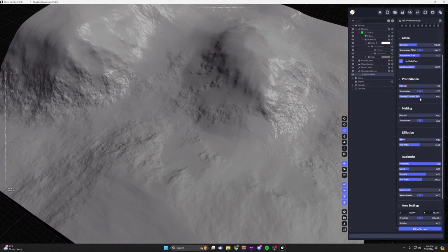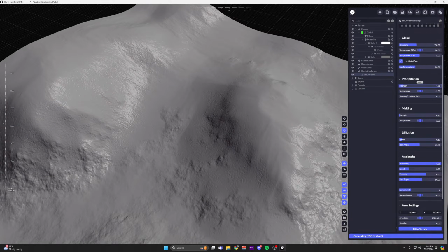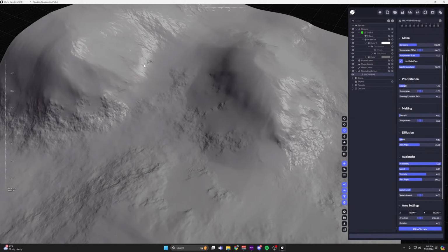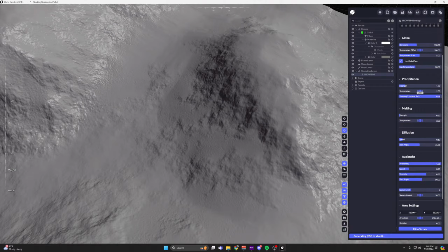So to understand, there's two different simulations happening. There is a sort of stable simulation, which is the powdery option right here. And there's the unstable, which is the avalanche stuff. So if you have it fully powdery, change it to 0, and perhaps increase the strength, you can add more snow on top of this mound. But if you want there to be some avalanches, or if you want that snow to not stick as well, you increase that ratio to be a little bit more unstable.